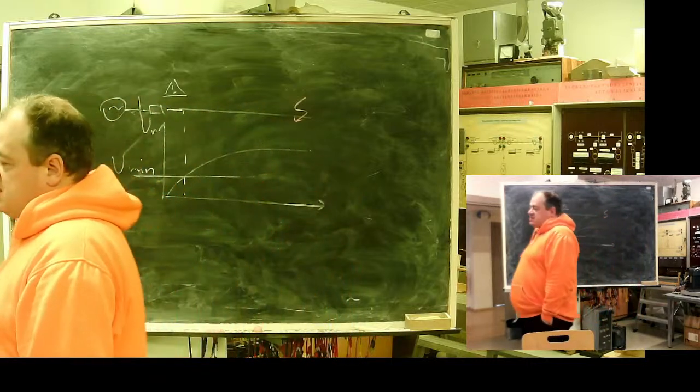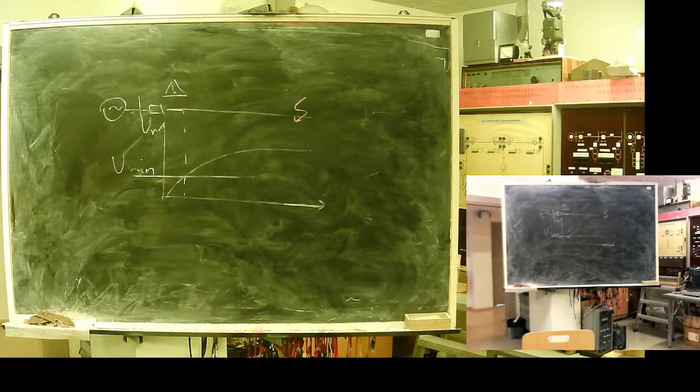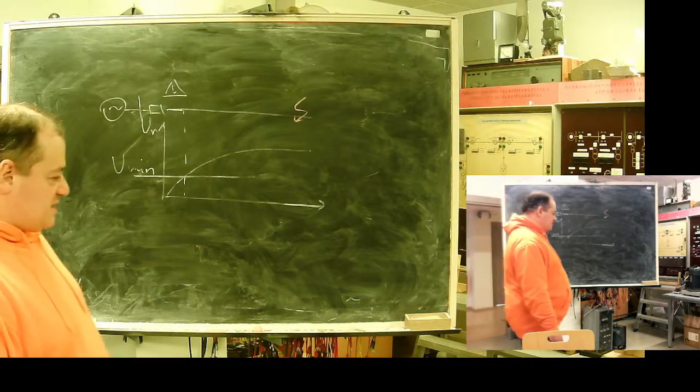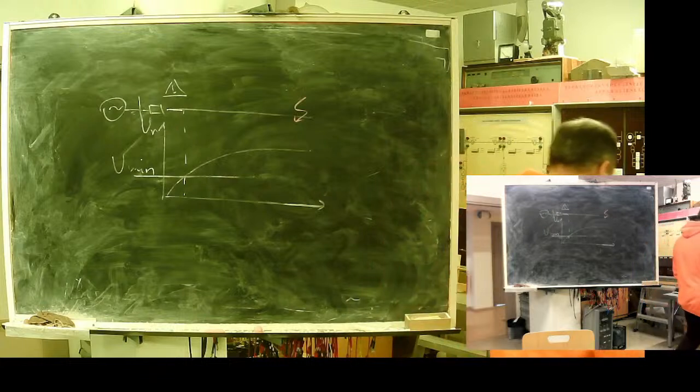For such a case, it's mandatory to equip distance protection with backup overcurrent protection. This backup overcurrent protection should be activated only for a small period of time after the switch is operated, while the memory of the main distance protection is empty, and on switch on fault condition it cannot operate.